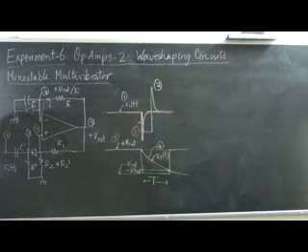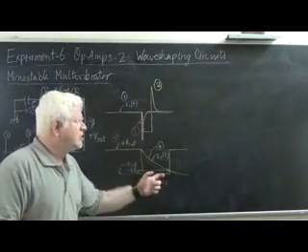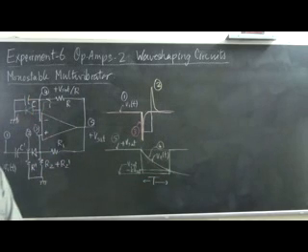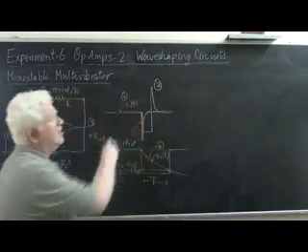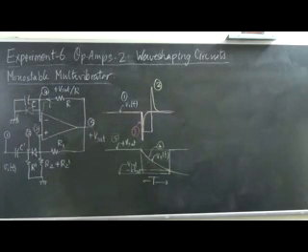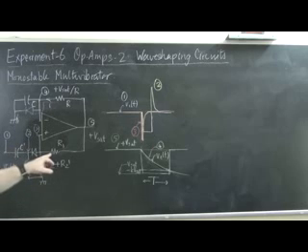The interesting part is this: the pulse width of the output depends only on k and on RC. It does not depend on the pulse width of the input signal. The input signal that is drawn as waveform 1 over here does not determine the output signal pulse width, because all that happens after all this processing with the diode and the high pass circuit here is that one negative impulse is extracted from this and passed on to the non-inverting terminal to cause it to shift its state.